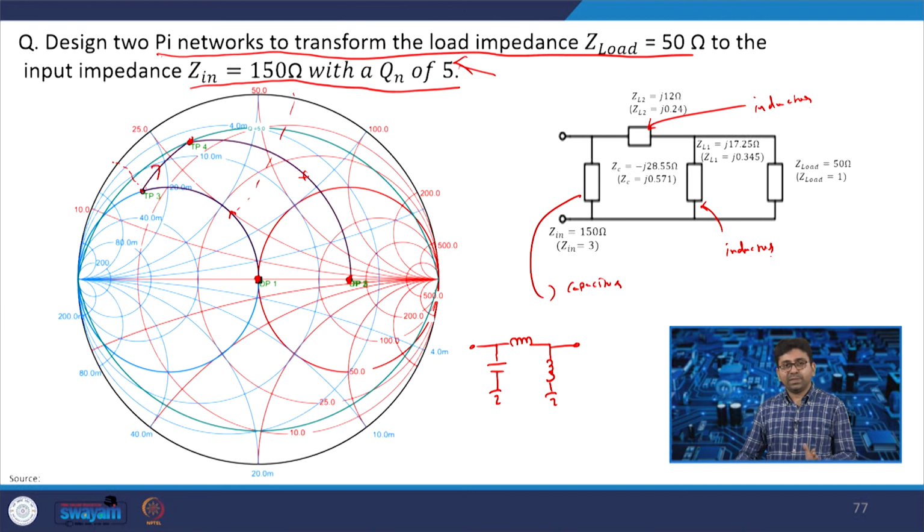So, this graphical method will provide you more flexibility in terms of choosing the value of inductor and capacitor. However, when I choose a T or pi network, I do not have flexibility in terms of choosing either capacitor or inductor. The placement of the capacitor and inductor will be the same, but we can find the values of them.